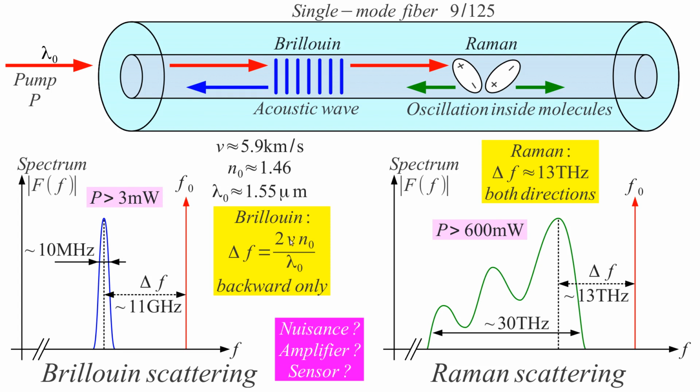The real problem is that Brillouin scattering happens already at very small powers, just a few milliwatts, provided that this optical signal is narrow enough. Well, most optical sources have a broader spectrum, so Brillouin scattering does not apply. But if we have a very good quality optical transmitter with a very narrow carrier, then Brillouin scattering may happen.